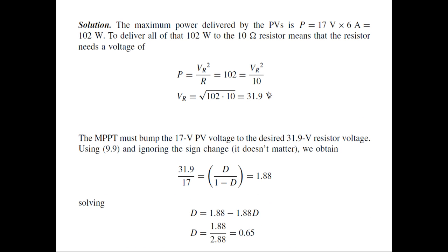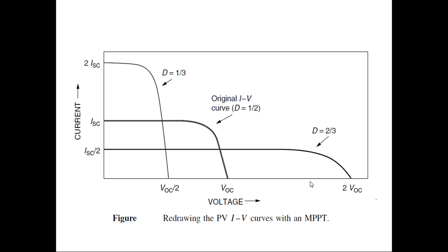This example proves that we have taken this as a boost converter. It concludes the same thing by considering two aspects. First, our output voltage is more than the input voltage, so it's a boost converter. Second, our duty cycle is above 0.5. If we can now conclude these prerequisites, this is the change in the voltage and current with the change in percentage duty cycle.